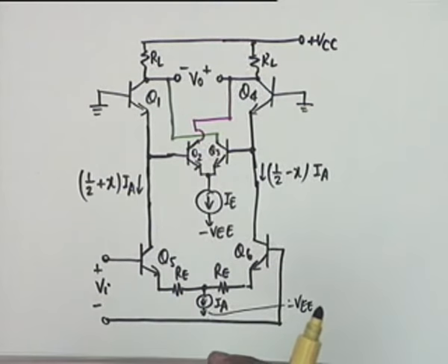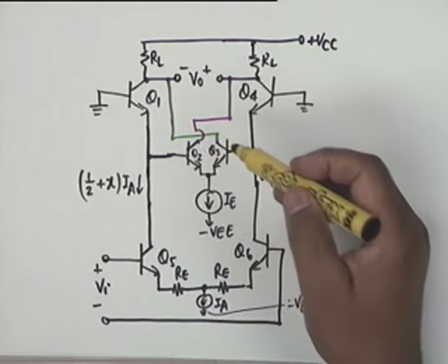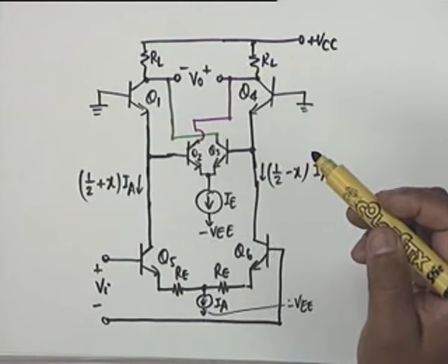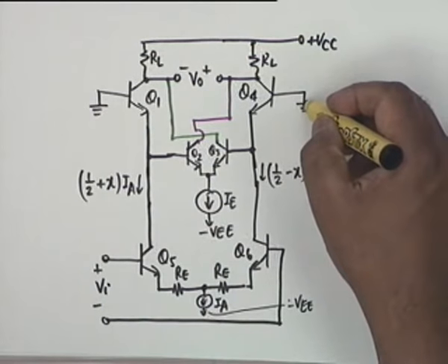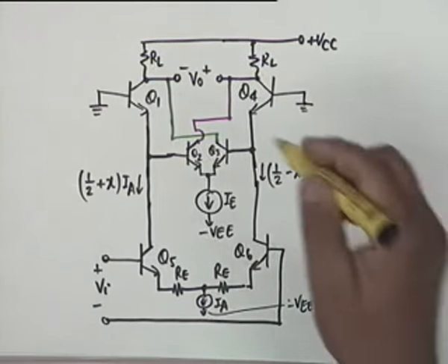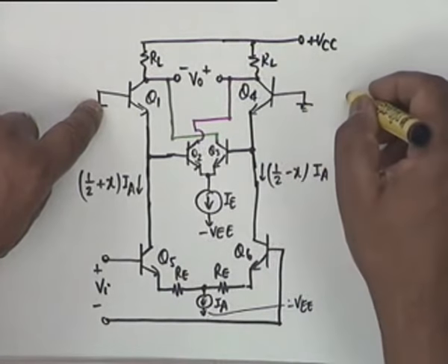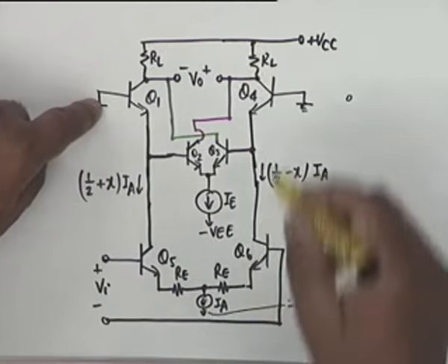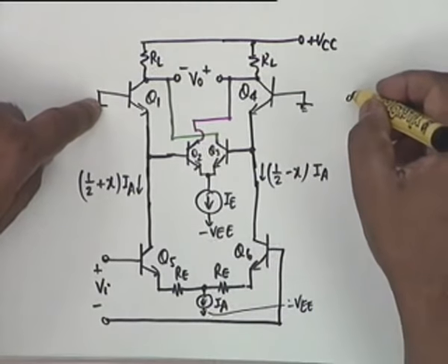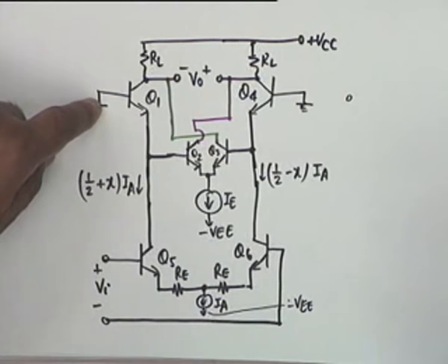With two supplies, then what about the bases of Q1 and Q2? These are grounded because, yes? So then we'll just take ground in the IC then. Oh, these two bases will be connected together, and a terminal will be brought out. In the IC chip of the Gilbert cell, a terminal will be brought out which you will have to connect to ground. Right? You will have to do that externally. There is no ground supplied in the IC chip.